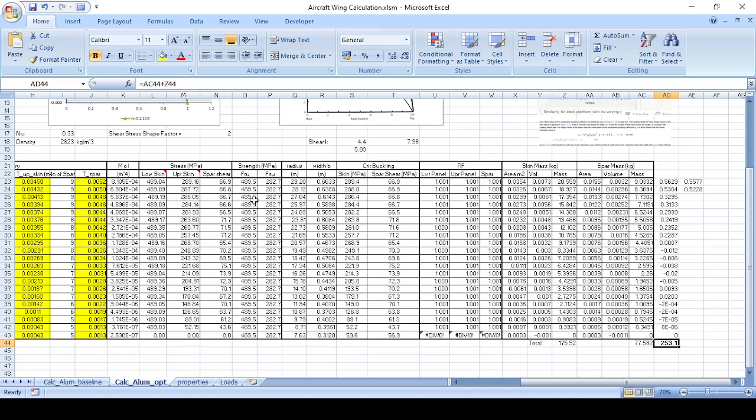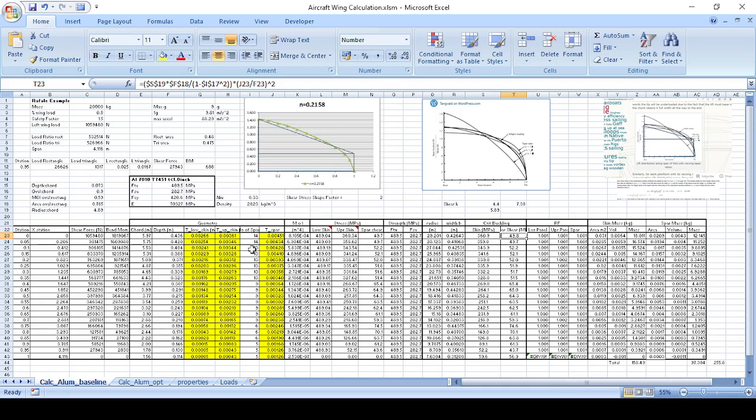In here I'm calculating the number of spars, and I've estimated the total mass for this wing based on the aluminium. There are no fasteners, no sealants and shims and all of that, so it's a very basic calculation just based on these thicknesses. I've calculated the number to be about 256 kilograms, and then I said, okay, based on that, can I actually improve on this design?